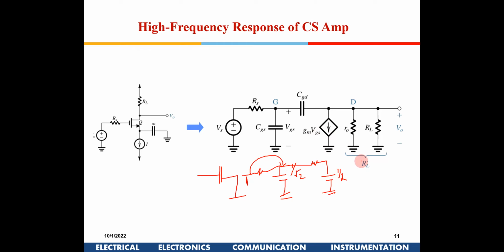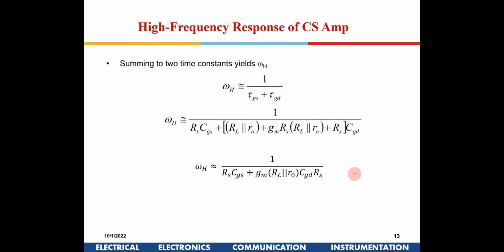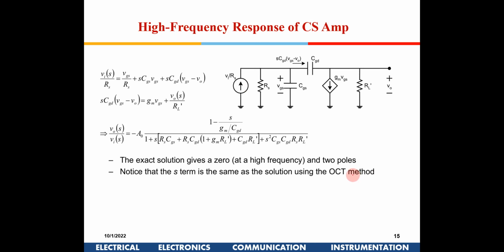As you keep increasing the number of poles, when two poles start acting together, that slope will increase. Initially the frequency is so low that you have not reached this particular frequency, so this is just bypassing it. But as the frequency increases, this also comes into operation. So the signal is getting attenuated 2 times. That is why the slope keeps increasing. So this is about the high frequency.